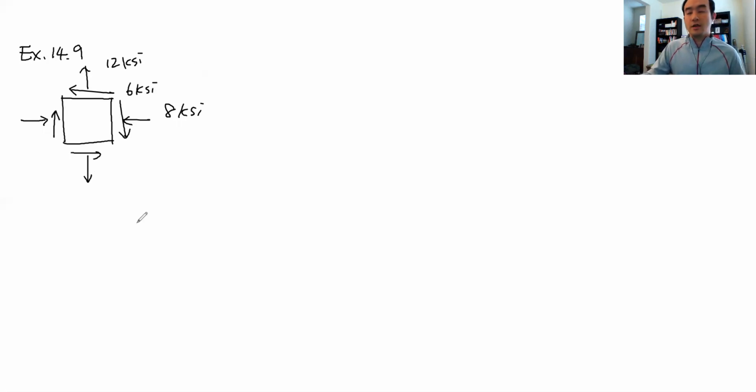Okay, so this is the state of stress. A state of plane stress at a point is shown in this figure. Represent this state of stress on an element oriented 30-degree counterclockwise from the position shown.